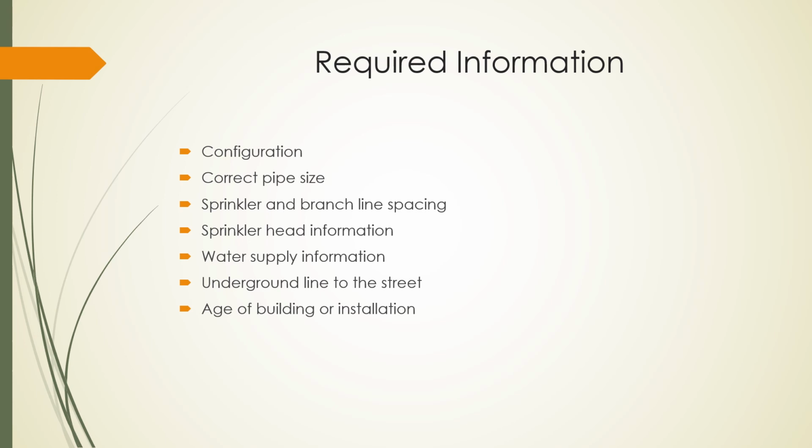age of the building or installation, which is really important because the age of the building and the installation tells us loads about when the sprinkler system was designed, and it gives us context to make decisions about how the system was constructed, because a 1960s building is not going to have an ESFR system, so we can rule things like that out. And it really does simplify the process by knowing the age of the building or the installation.